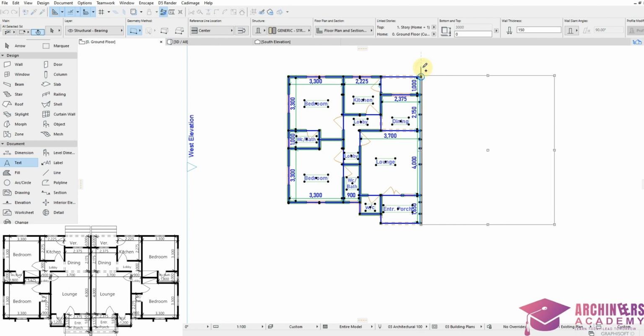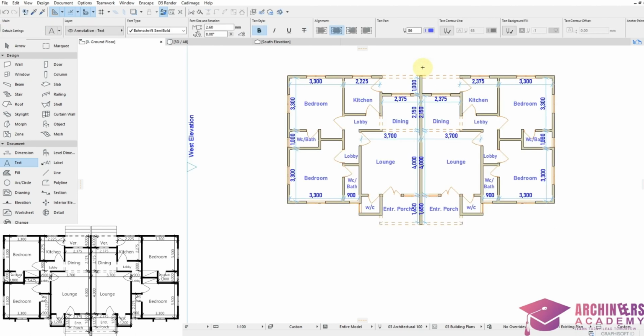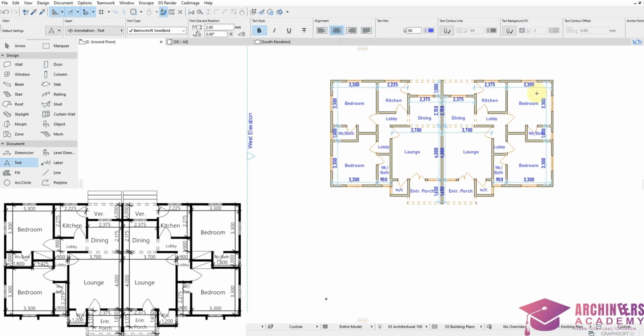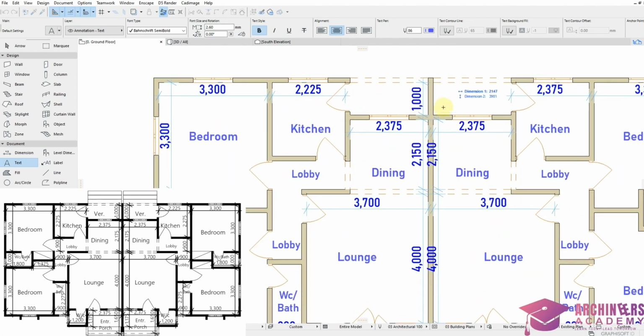Then you click. So you are seeing it. It has automatically created a mirror of this design. Because in semi-detached designs, the two different buildings or the two different apartments are a mirror of the other one. So to easily get it done, just finish designing one part, then use the mirror tool to get it done as easily as possible. Creating both at the same time would be a lot of work. So you can see how quick it is if you make it a mirror.